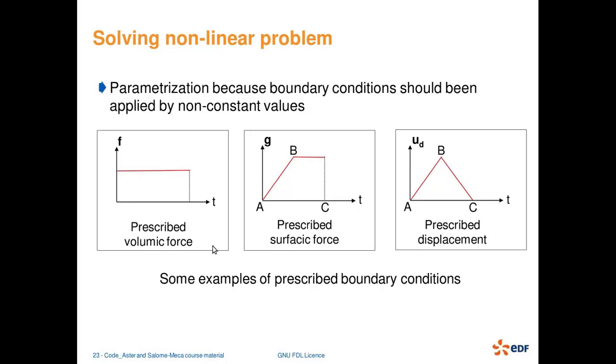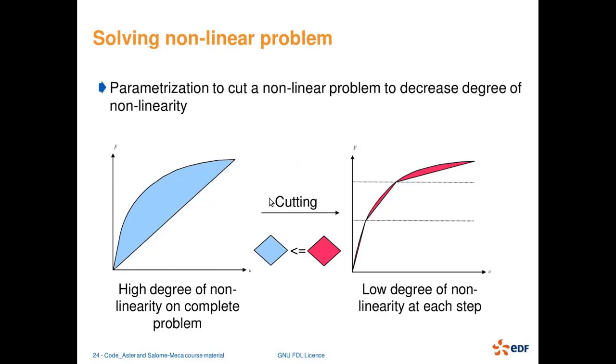You see the boundary conditions like prescribed force or prescribed displacement may not be constant. It may change with time like this. These are some examples of that. And in order to apply these kinds of boundary conditions, we must express them as a function of time. Secondly, a nonlinear problem, if we try to solve it in a single step, then my solution will not be accurate.